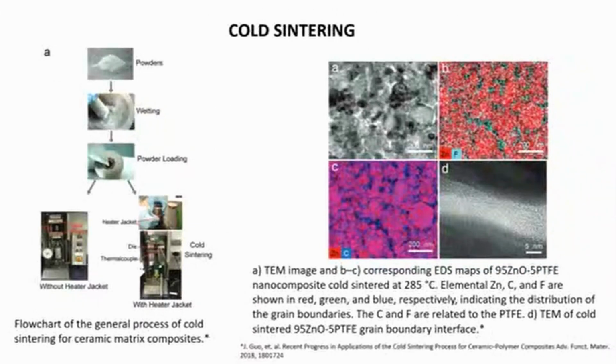And finally, I will show you the novel technique called cold sintering. Cold sintering process is a non-conventional, low-energy sintering technique that promotes the densification of ceramic in the presence of transient liquids under low temperature, below 300 centigrade, and pressure below 500 MPa, megapascal.